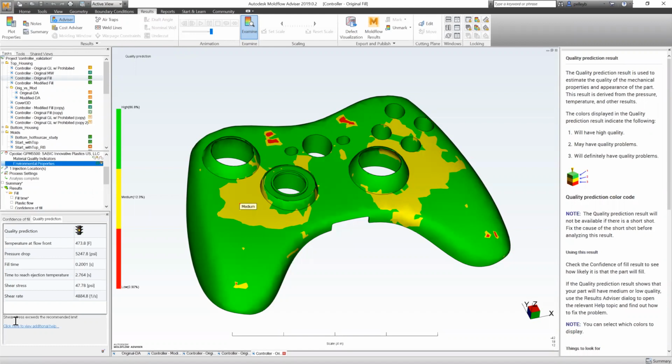One thing I can say is, for shear stress, shear rate, it's putting the molecules in tension. So those are areas that are prone to chemical attack or breakage because they're in tension. And so we want to look at that from a mechanical level. A cosmetic aspect could be even more severe. So we might have to back down on this threshold, as far as what the max level is is arbitrary. You need to really use this as a guideline to your specific application.